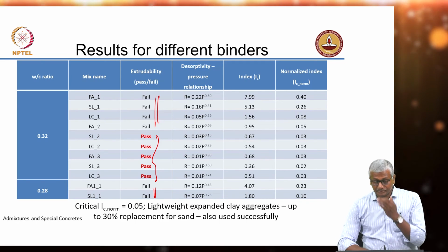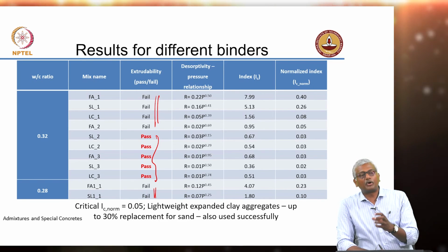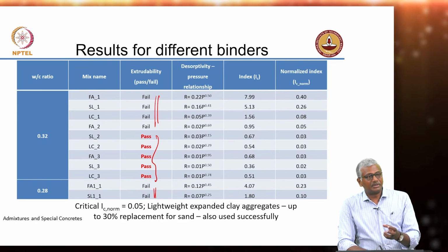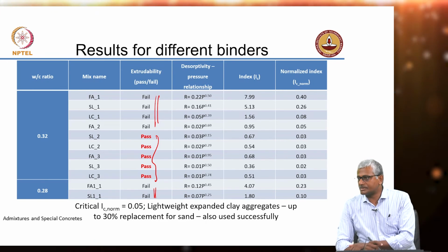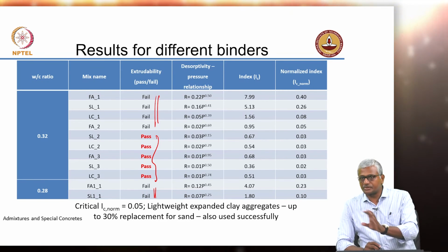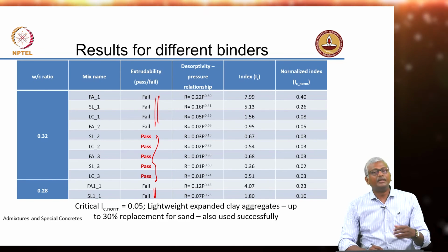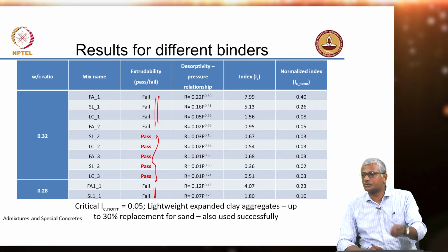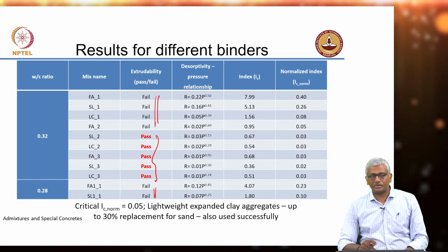So, the idea is that one has to be able to assess the possibility of liquid phase separation when the system for delivering concrete to the nozzle changes. It's not required to be done in all the cases, but when your printing system is changing, you need to build in additional safeguards to ensure that the mix that you've chosen will be capable of handling that operation.